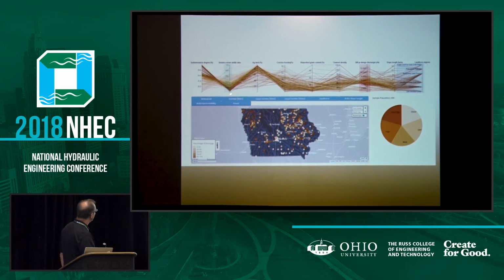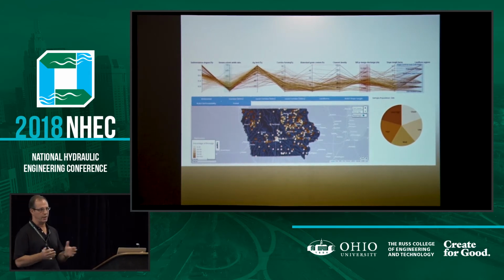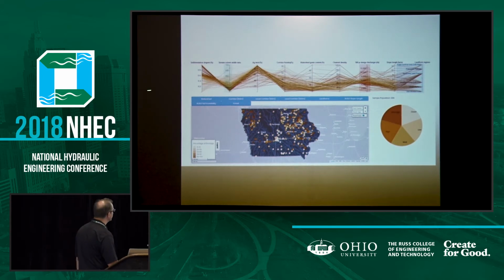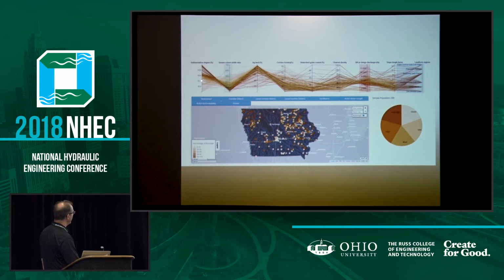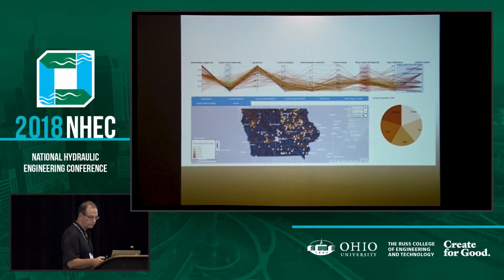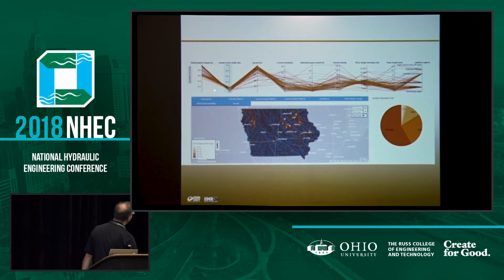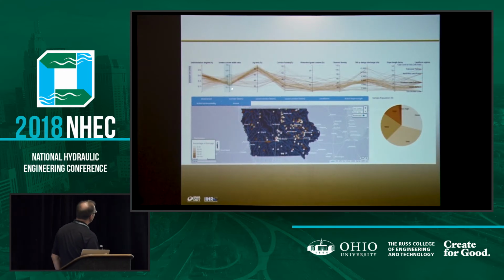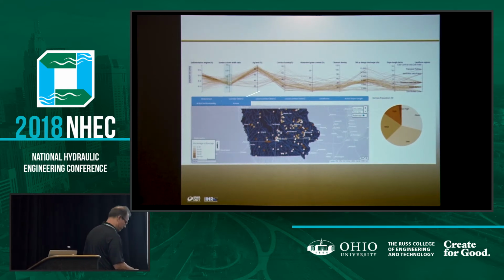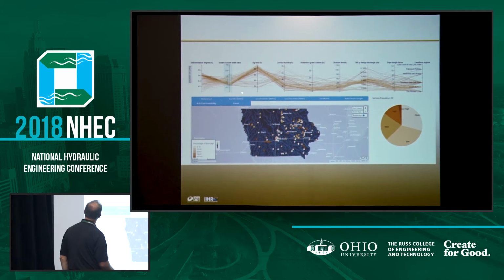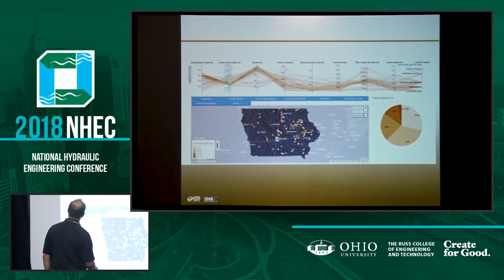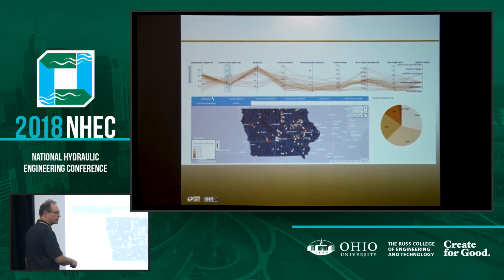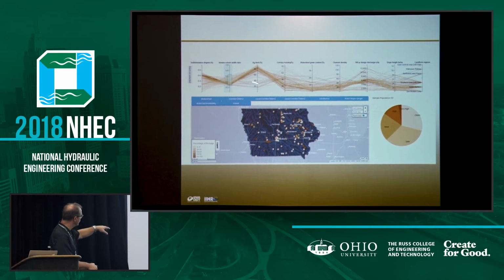The first thing I just want to point out that I talked about is the stream to culvert ratio. The lower the ratio, or the lower the percentage, let's say the stream is only 20% of the total box width. When you have that situation, no matter what kind of landforms you have, you're going to have a high potential of sedimentation, okay? Now let me go to the next one. So let's say we have a slightly higher stream to culvert ratio. And as we increase that, you can see that the sediment potential starts to go down, right? Because this is high and then down here is low for sediment potential.